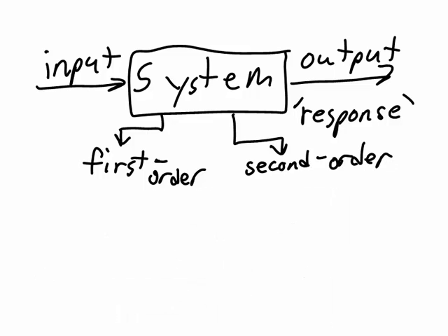We learned that systems of the same type behave or respond in the same way. All first order systems have a response that is defined by their time constant, while all second order systems have a response that is defined by their natural frequency and by their damping ratio. By knowing just these few simple characteristics of a system, we can predict many important aspects of the system response to a few standard inputs: the impulse, step, ramp, and sinusoid input.